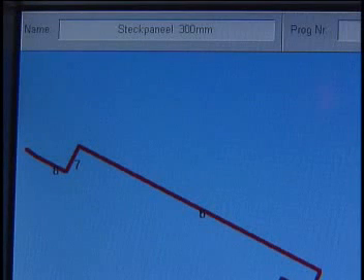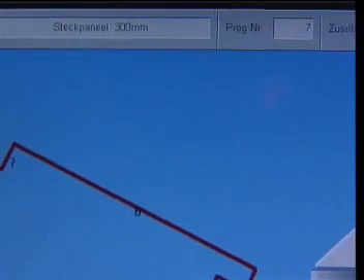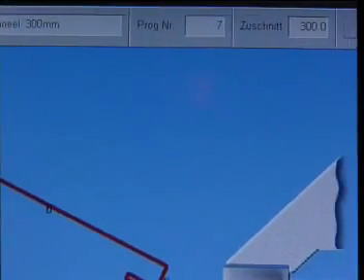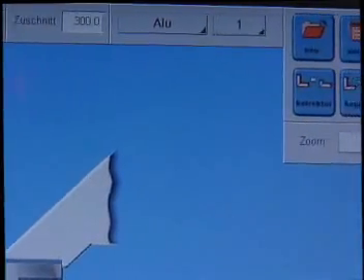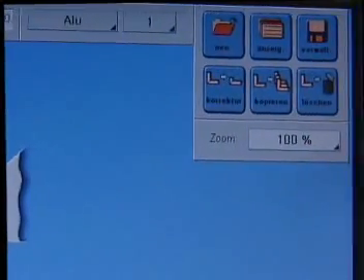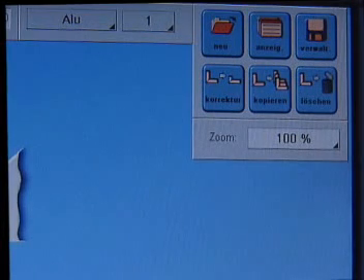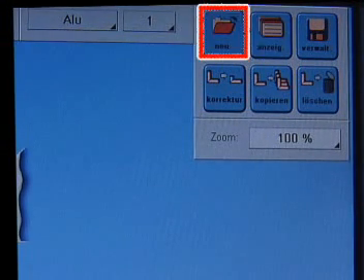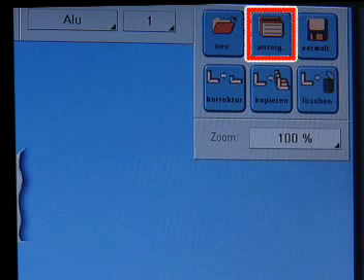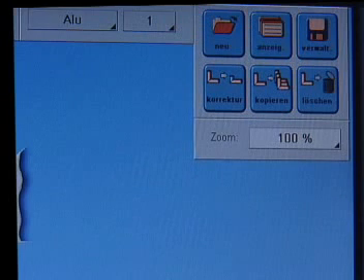The main screen has different groups of buttons. On the top end are the profile headers with program name and number, cut size, a pull-down menu with a choice of the most common materials, and allocation of material thickness from 0.5 up to 6 mm. In the top right corner are the program administration functions for creating new profiles and for listing and searching profiles. The Admin button leads to all submenus for system administration.